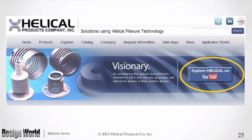But it also has videos regarding torsion springs. It's something we're going to talk about in just a minute. But the torsion springs video is good in the sense that there is a moment issue with torsional springs in regards to tangs. When you have a wire spring and a tang and you put a force in that tang, you get the force, you get the reaction that you want, but you also have a moment or a translating force, I guess, that you have to account for. And there's an example of what that is too. So when you get a chance, take a look at these YouTube videos so you can better understand what I'm talking about.